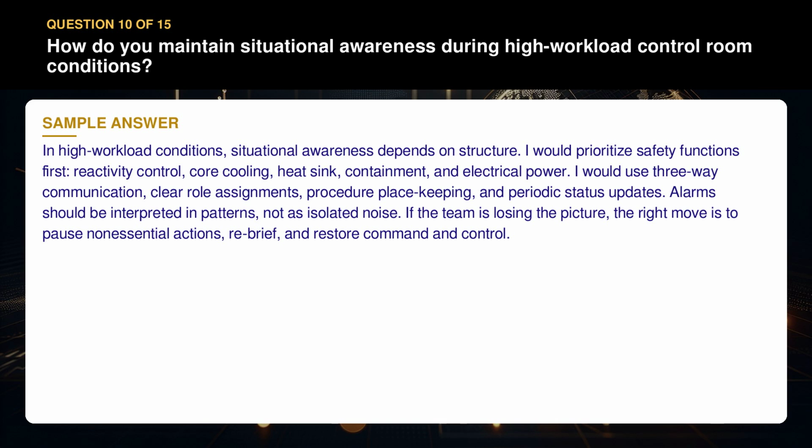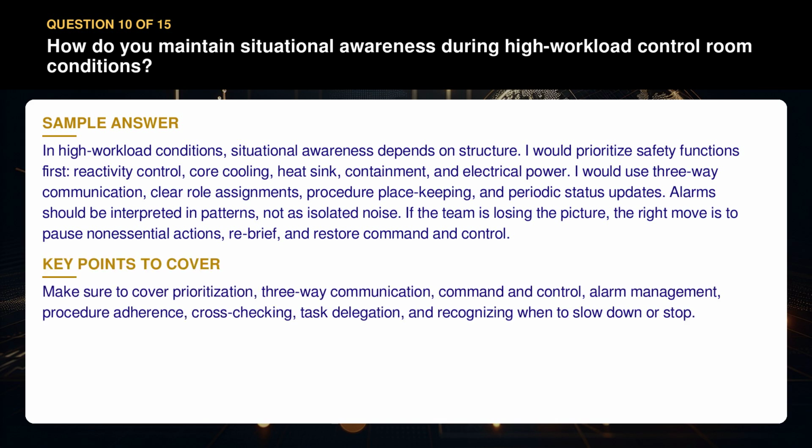Alarms should be interpreted in patterns, not as isolated noise. If the team is losing the picture, the right move is to pause non-essential actions, rebrief, and restore command and control. Make sure to cover prioritization, three-way communication, command and control, alarm management, procedure adherence, cross-checking, task delegation, and recognizing when to slow down or stop.